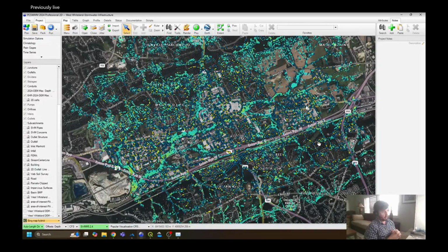Right now, the workflow in HECRAS 6.6, the two advancements in it are you can import in your mesh from the new tool. It's a major improvement. And you can import in SWM models, the 1D elements and the 1D assets made in SWM. You can import those in to HECRAS 6.6. I believe you can build them yourself in 6.6. I haven't tried it out, and I can't really comment too much about the workflow there.